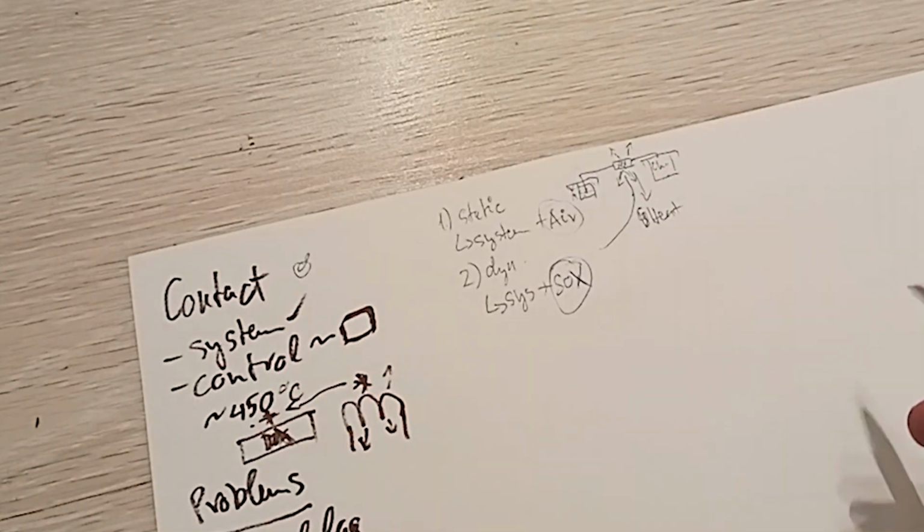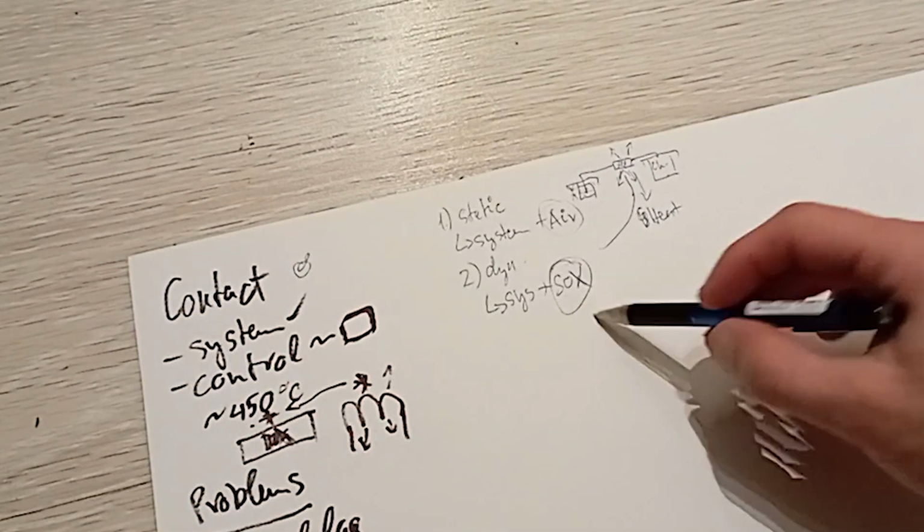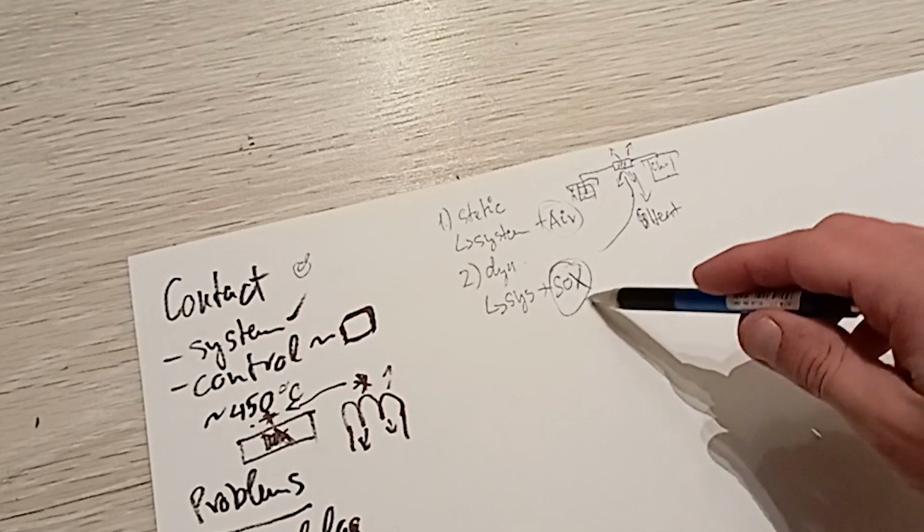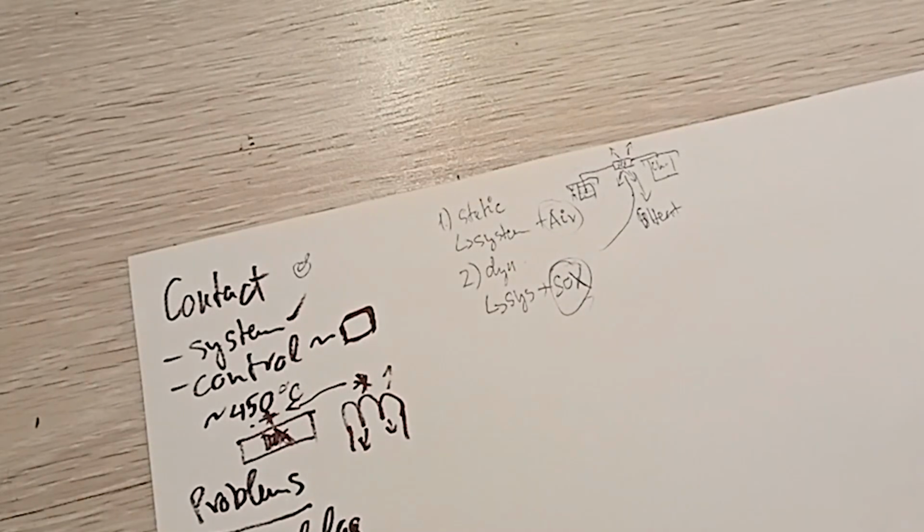It likes to be heated up before it starts to liquefy, then it can be lit. The problem with that is that it can change how much sulfur I burn, and the concentration of sulfur dioxide in the mixture dictates how much heat is produced. So this is not constant. This depends on time, temperature, moisture level. This can change every single day.